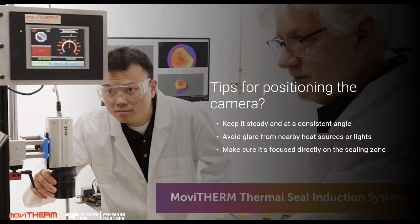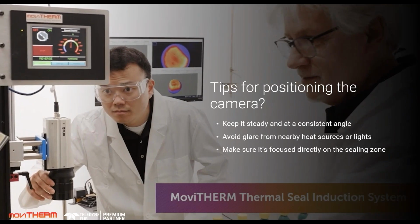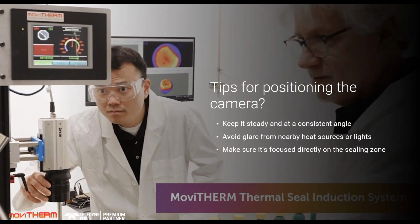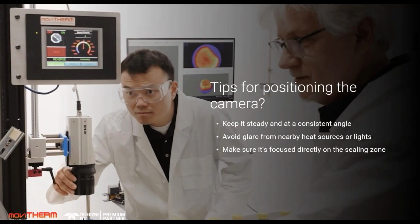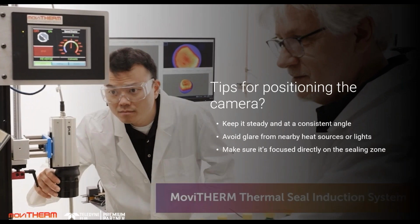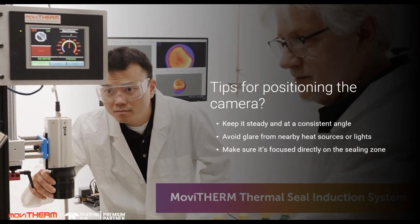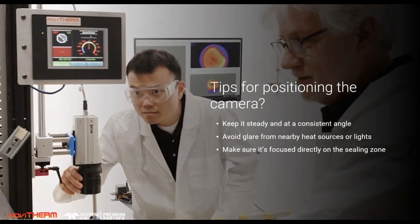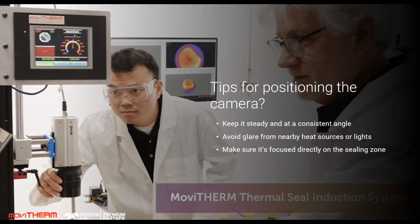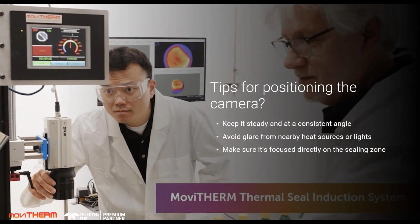We want to fill the field of view as much as we can with the cap. So you could see in the video, you want to have some Z-axis control for different heights of the bottle. A lot of times we'll move the camera up and down in case of different heights, because we do want to have that cap fill the field of view as much as we can. And essentially, those are about the only tips.